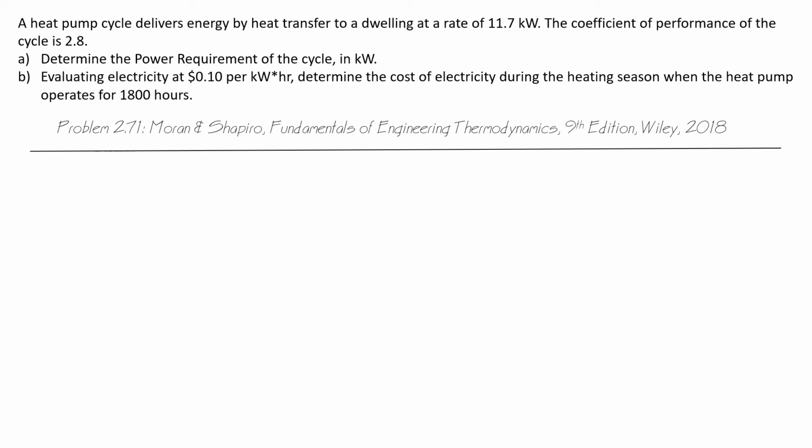Determine the power requirement of the cycle in kilowatts, and evaluating electricity at 10 cents per kilowatt hour, determine the cost of electricity during the heating season when the heat pump operates for 1,800 hours.